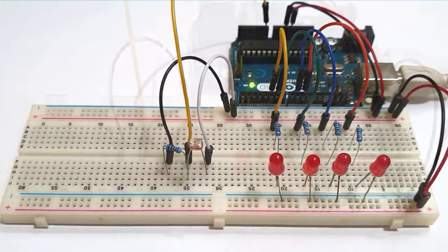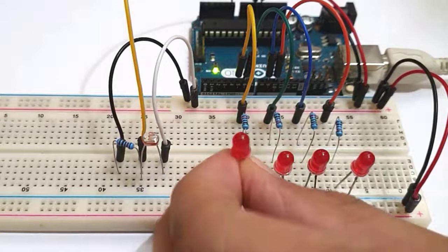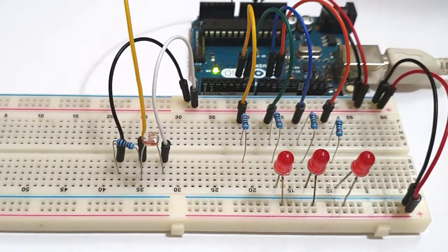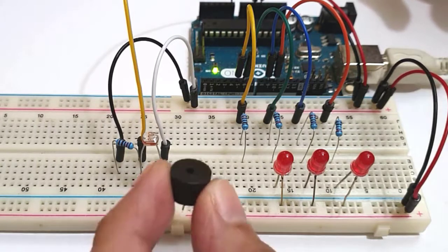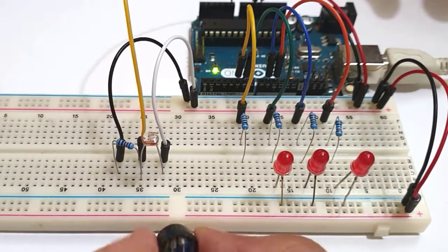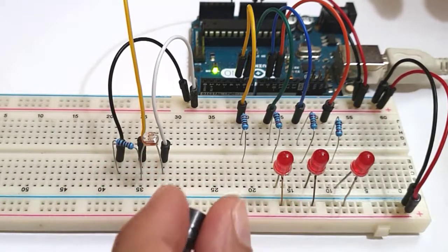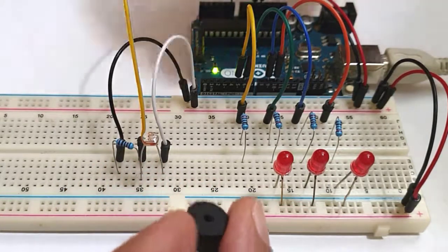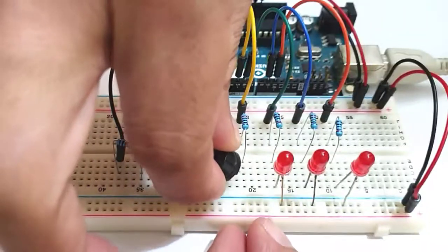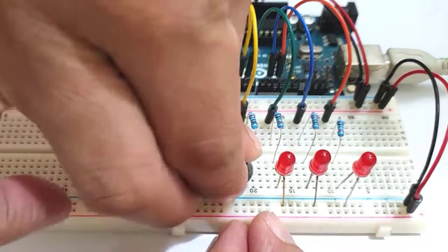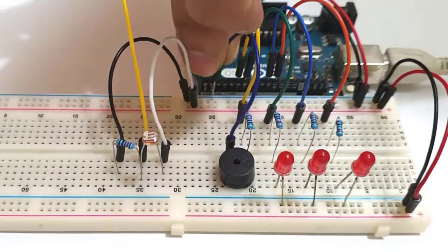And now, for you not just to see the effect but to hear it, I'll remove this LED at pin 5 and replace it with a piezo buzzer. It has a positive and a negative terminal as well. Inside this piezo buzzer is a coil of wire and a small magnet. When current flows through the coil, it becomes magnetized and pulls toward the magnet, creating a tiny click. When you do this hundreds or thousands of times per second, you create tones.